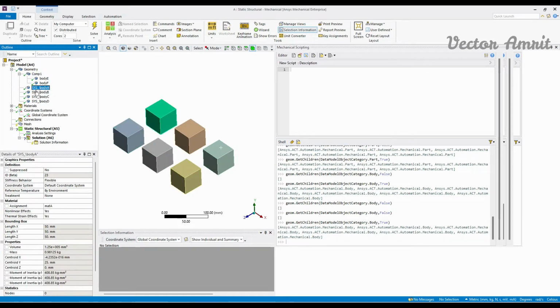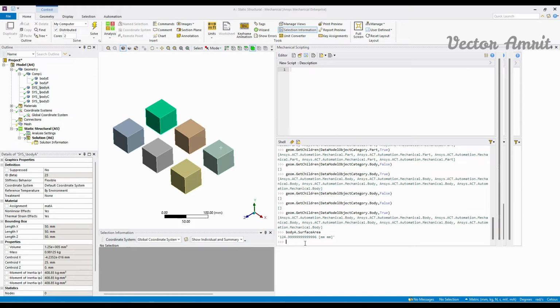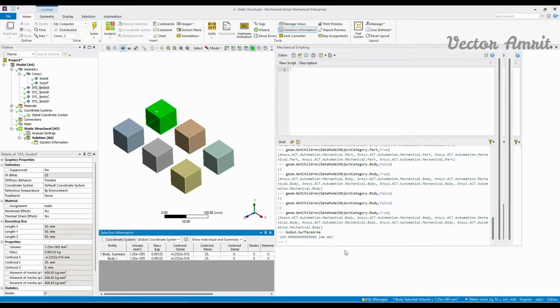Okay. So when you select a body, if I do body A, which we had assigned before, I can access surface area. I think it will be the wrong surface area. A body should not return a surface area. It should return a volume. Okay. I think it's for outside surfaces. I'm not sure on that. So you cannot access, for example, this body has 6 faces, right? And almost 12 edges are there. So you cannot access them through this model object, the geometry data model object. So at that time, you need to enter the geo body of this.